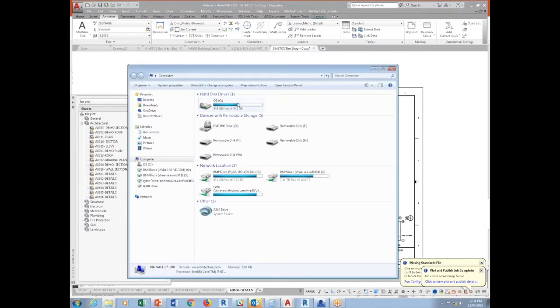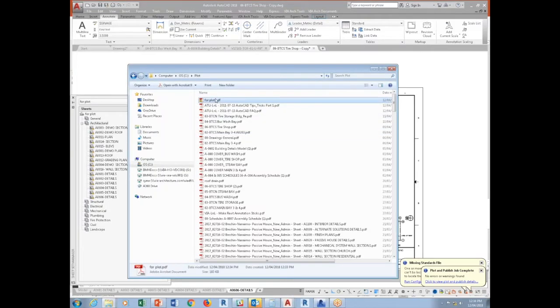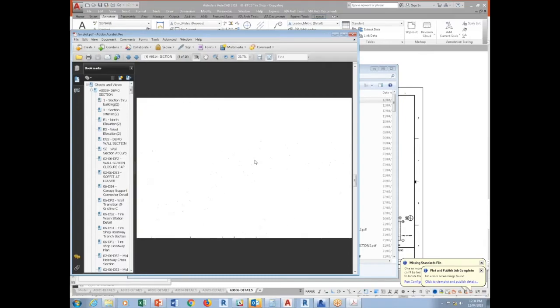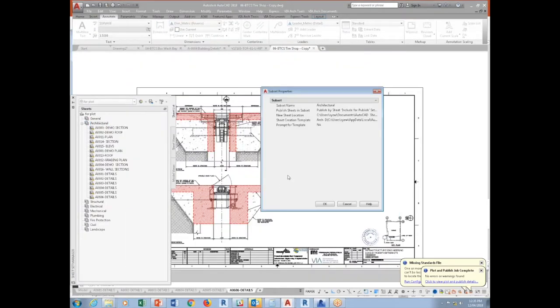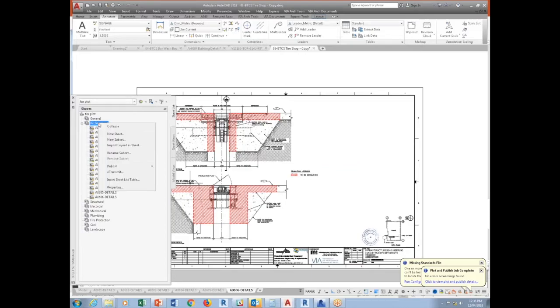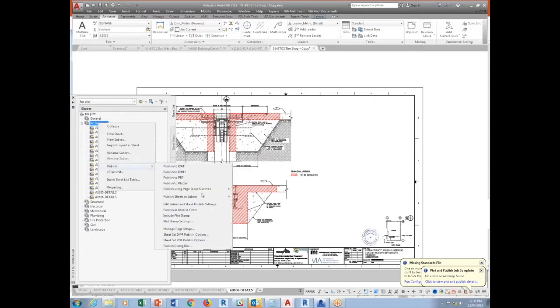So the nicest thing about this is that once I plot it and finish it, it's going to place it here for plot. Okay, I didn't do it correctly. You know the reason why, right? It's because I did not set the scale. Something to just be reminded of, all right? So that's okay. This is just for demonstration. But if you want to change it, this is how you do it.